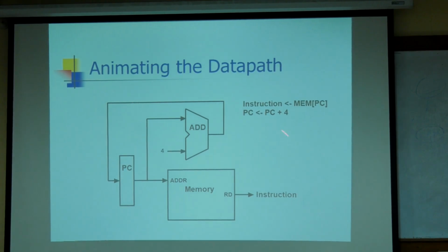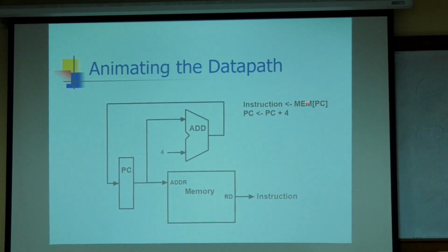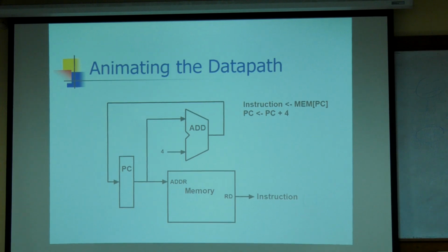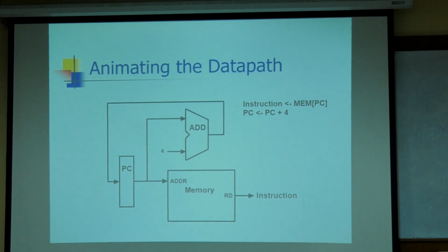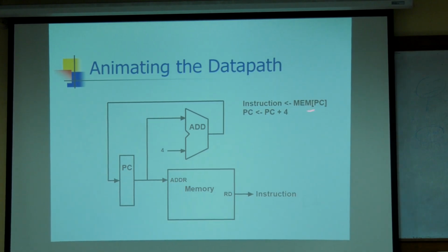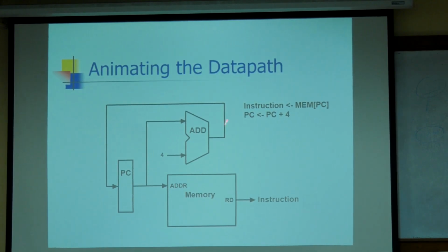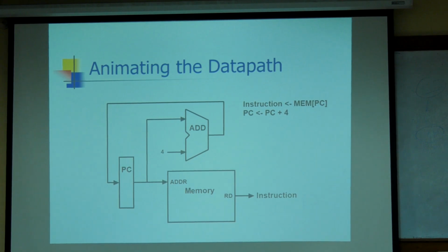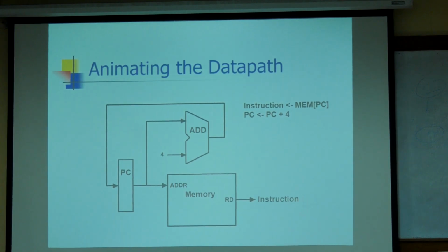If you see this, you can also verify it: the instruction PC equals PC plus 4. PC is the program counter. Every time it is incremented by 4. First, the PC indicates the current instruction. PC will be automatically incremented by 4 to indicate the address of the next instruction.